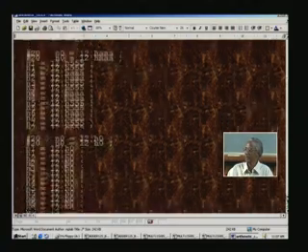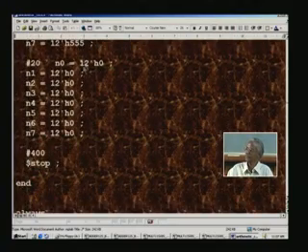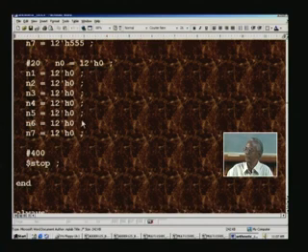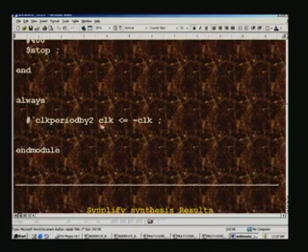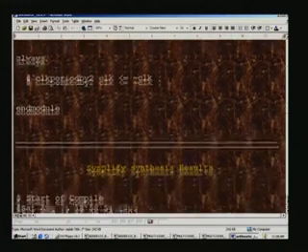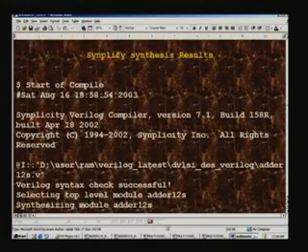And once again, I think this is the final thing, we have all zeros here, and after giving some cushion of 400 nanoseconds we stop, and this completes the test bench. And we have finally in the test bench the toggling of the clock, and this is the statement which is responsible for making a free running clock using an always statement, and the module ends here. Before we go on to the simplify results, which is here, we will first see the waveform.